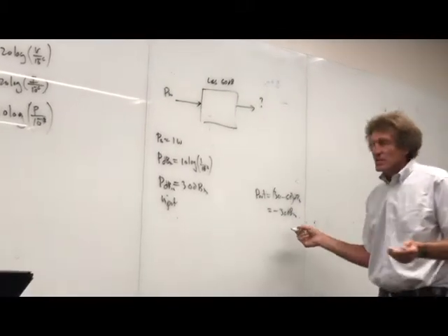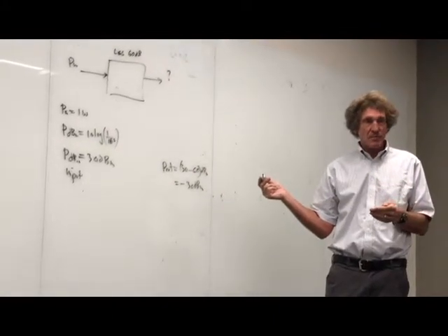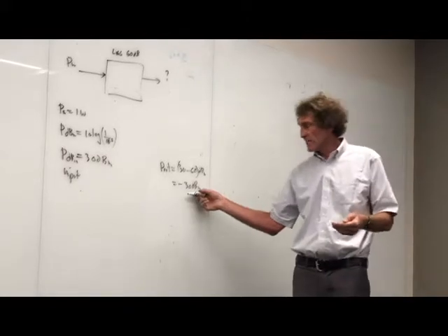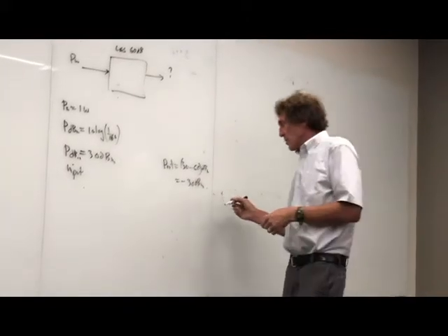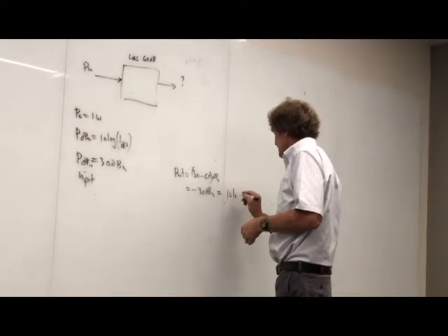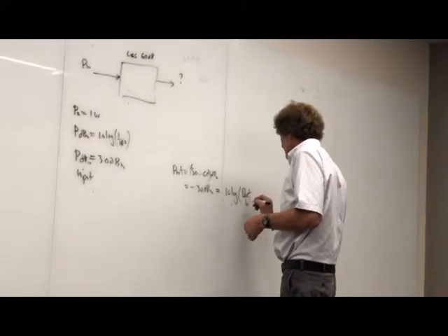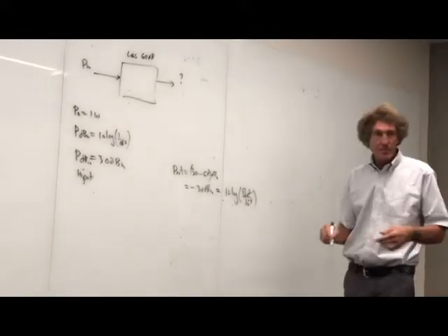Now, translate that into how much power in watts. Do the inverse problem. If I got an output of minus 30 dBm, what does that mean? That means I have 10 times the log of whatever the output power is over 10 to the minus third. You all see what I'm up to here?